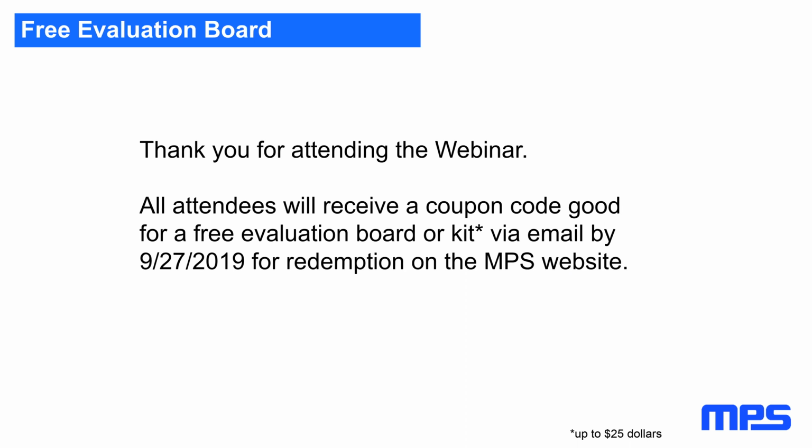Next question: on your earlier slide, when you improve the layout on PCB2, is there only one via connection between local ground on layer 2 and the ground plane on layer 3? Or maybe that was layer 4. Will that be good for DC current, and is there a good preferred location for this via connection?